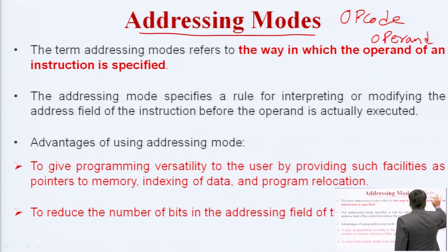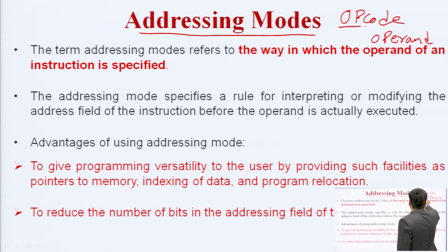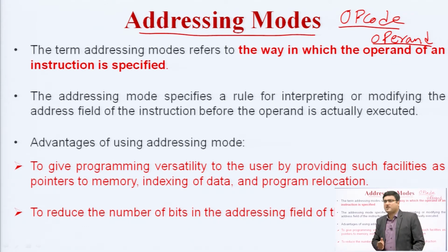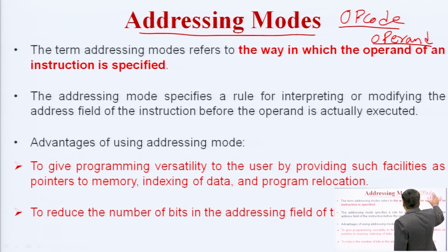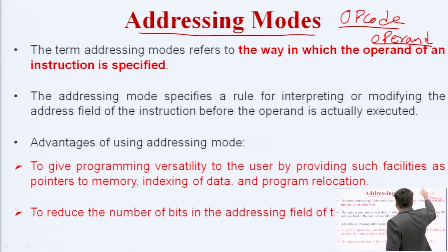If we look into the instruction of any microcontroller, there are two things in any instruction. The first one is the opcode and the second one is the operands. Opcode, or operational code, which we can also call mnemonics or machine codes, tells the microcontroller what to do with the instruction. And operands are what the instruction is to be executed on. If the opcode says that we have to move some data from one register to another register, on whom will it operate? It will operate on the operands.